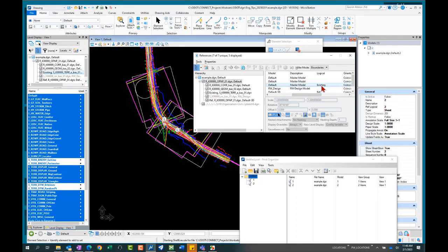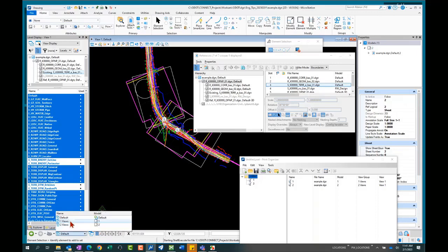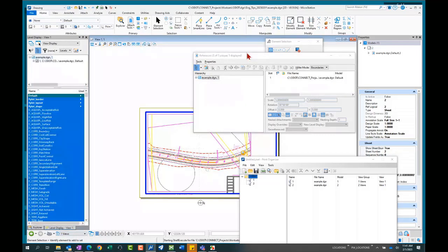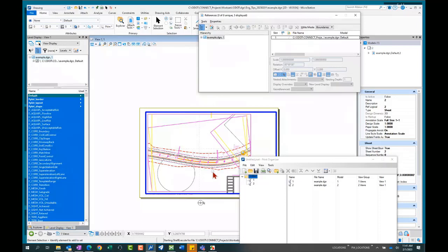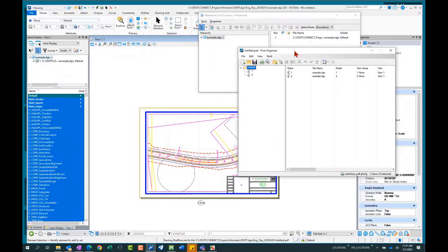Now, it already has the logical name of exist. So when I view this information through the sheet model, now that I've turned it on in the default model, it should show up. Let's try it. I'm going to open up the number 1 views, and I don't see any change. So I've been told that if this happens, you should reopen the file and it might update.